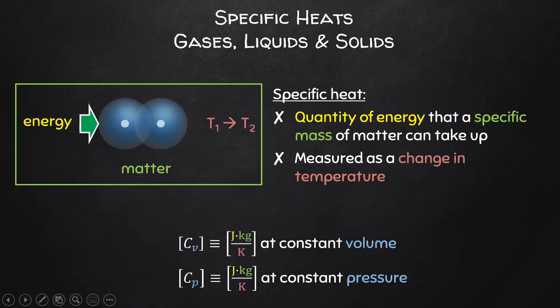Right, another property that we tend to often deal with as chemical engineers is that of heat capacity, or the specific heat of substances. It is helpful to understand how this property is measured in order to understand what it refers to. And I like to do this with other physical properties such as viscosity. It helps me to remember what these physical properties refer to. So if we consider a quantity of energy that is supplied to a specific amount of mass, we can measure by how much the substance will heat up.